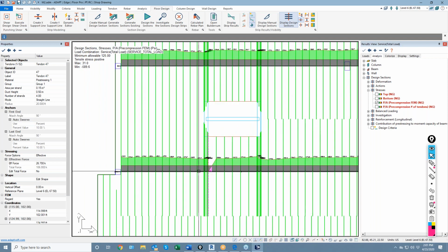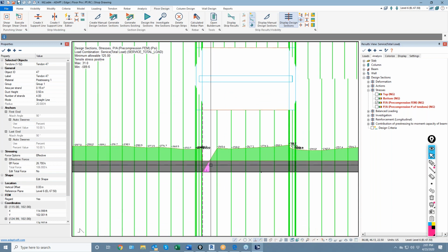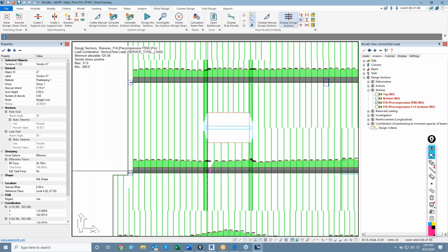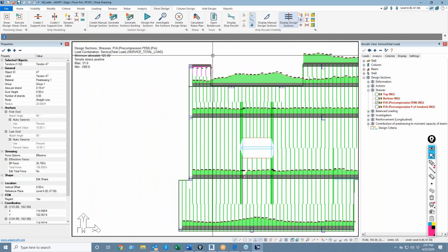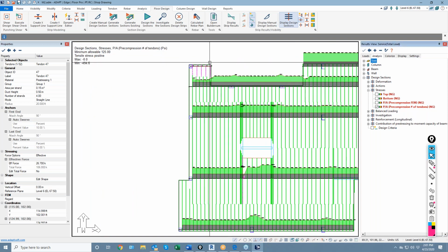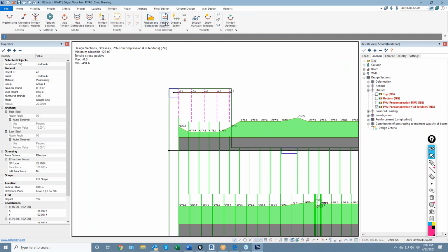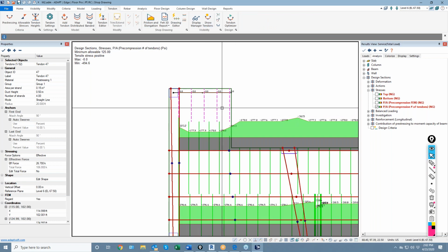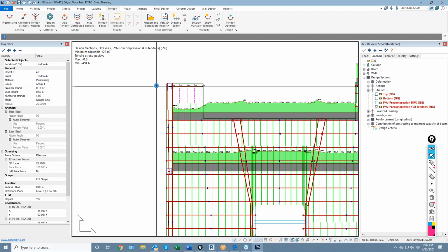You can see right here, there's some strange result there where I'd have to go through and check out why that's happening. But that might be more of an anomaly in terms of the actual solution for that node in the general solution. Up at the top, I'm going to go back to number of tendons. At the top, you can see these are all flagged as 0. This is an RC section of the slab. There are no tendons that actually cut that location, so those get flagged as 0. The code check says, oh, those are no good, but in reality, this is really an RC location, so we're going to ignore that in this case.